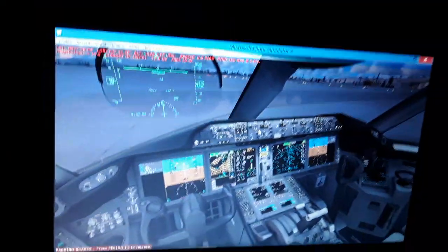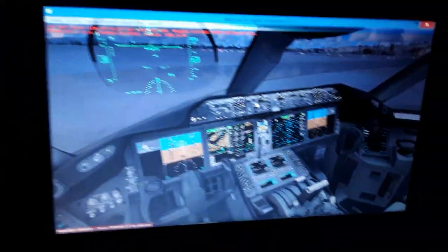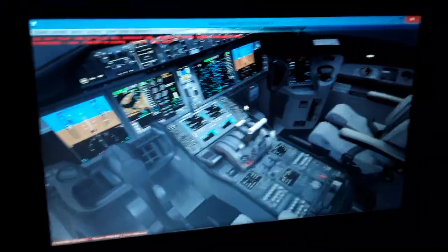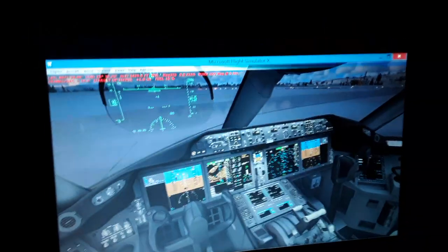So we're gonna have the STARs, the standard terminal arrival waypoints and fixes for the terminal arrival and approach and landing of the aircraft into the airport. And the ILS localizer, the instrument landing system, we're gonna tune the ILS localizer, horizontal and vertical navigation, the needle and the glide slope, and the crossbars. We're gonna have this automatically using the flight management computer, and manually we can do it using the radio management panel.